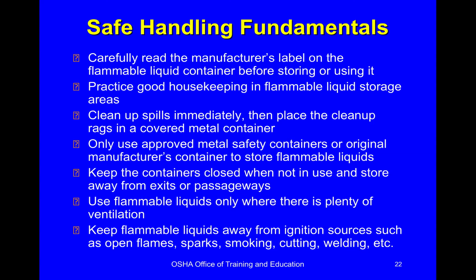Keep the containers closed when not in use and store away from exits or passageways. Use flammable liquids only where there is plenty of ventilation. Keep flammable liquids away from ignition sources such as open flames, sparks, smoking, and cutting and welding.